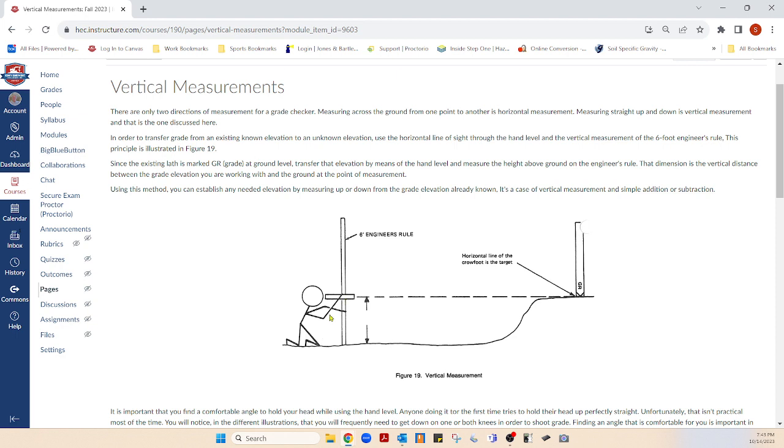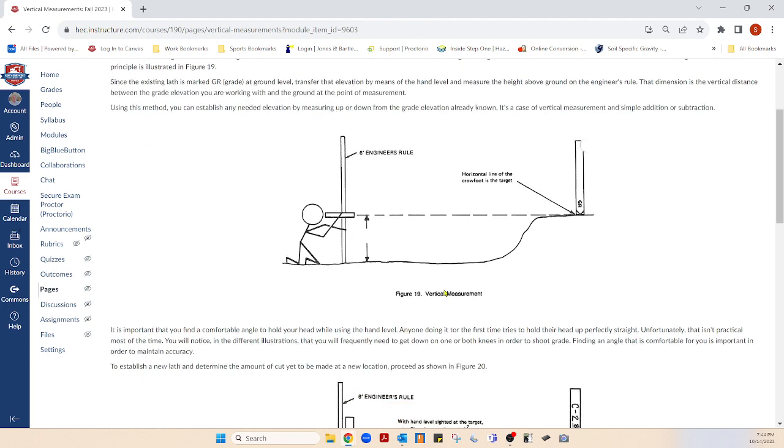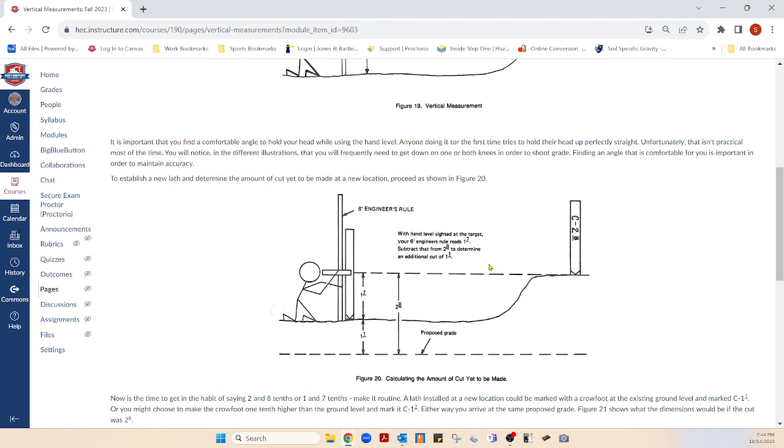Now that's where I'm messing up. If this ground was lower and it measured 3.5, the fill would be 3.5. I think I've complicated it, but perhaps I can straighten it out and say, let's say this ground went down lower than that, and this turned out to be 3.5, he reads on here. Well, that would be a 3.5 fill. Let's move on, because we've got more and more of this.